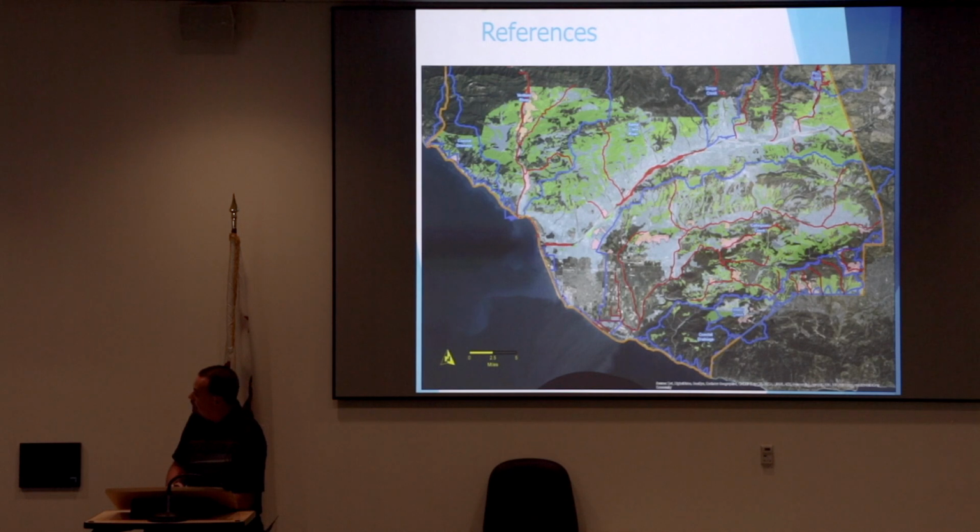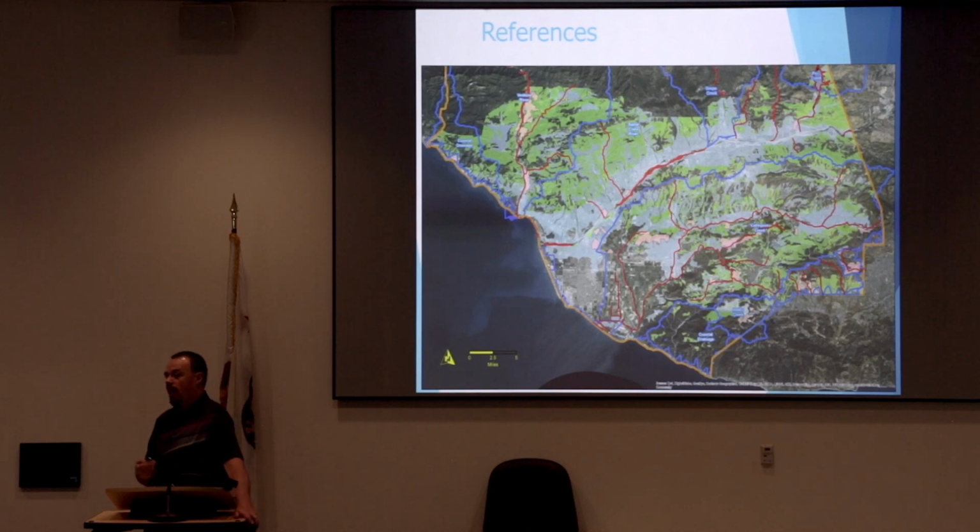Unfortunately, it's right along the creek beds generally. So a lot of the times it's not right next to where you need them if you need to do infiltration. But it's a good reference point again for different areas to see, okay, well, I think I should be able to do infiltration here. We should do our concept design as infiltration until geotechnical shows us otherwise.